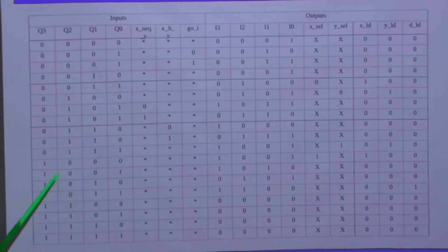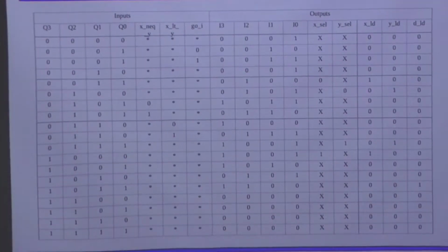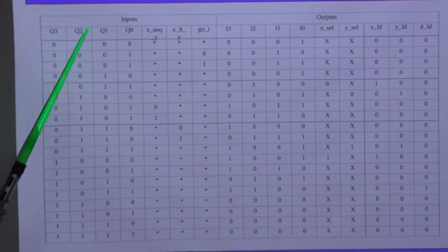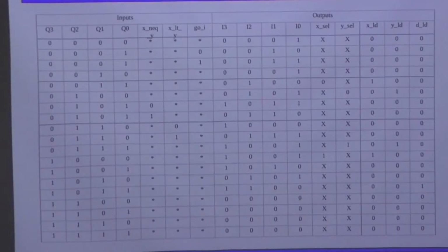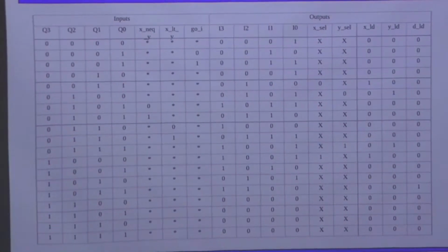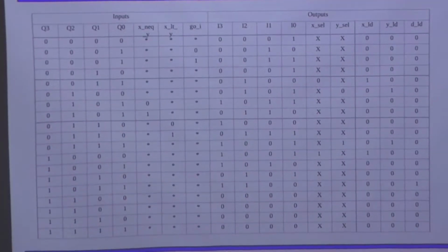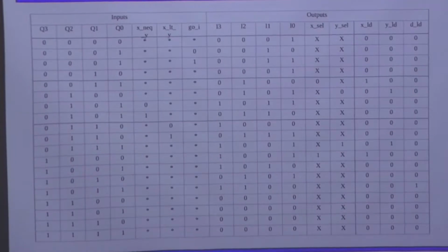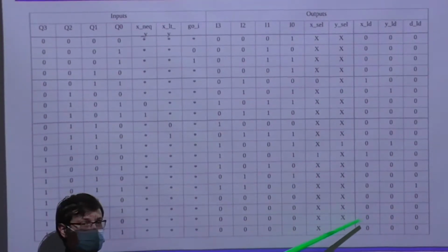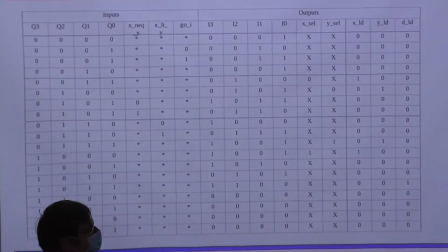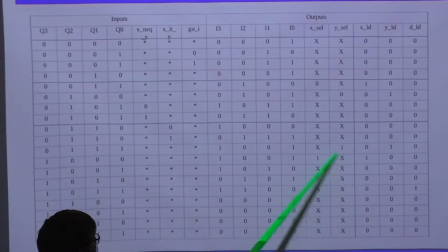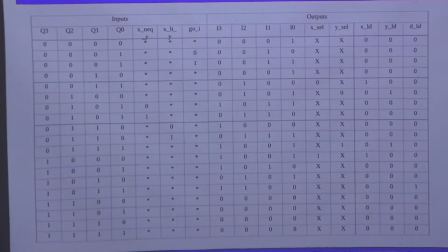This state table represents the combinational logic that we need to derive for the controller itself, right? Our first and primary inputs to this process are the 4 bits which represent the current state value, right? So we notice that we're basically just doing binary counting through all of this. Let's consider the X load output itself. We notice that we are only loading in state 3 and in state 7, or 8.